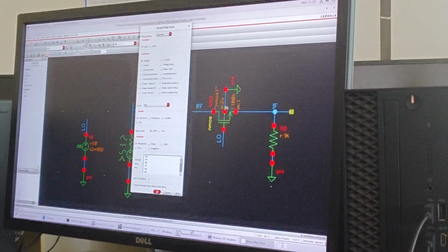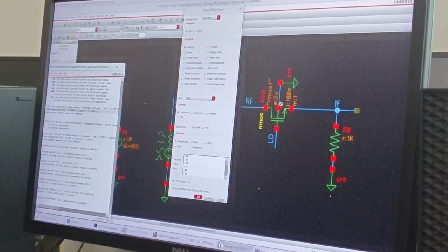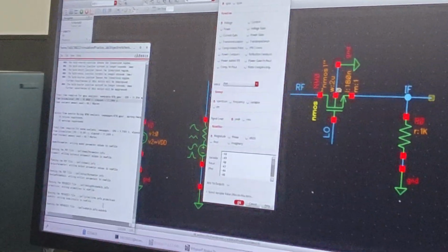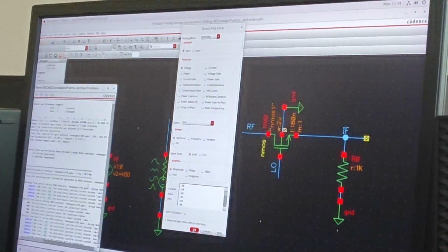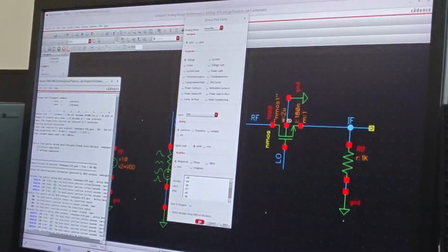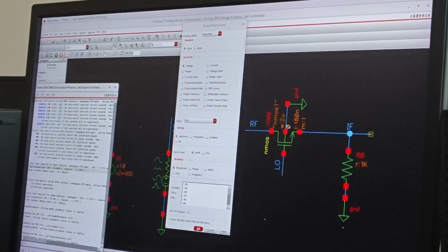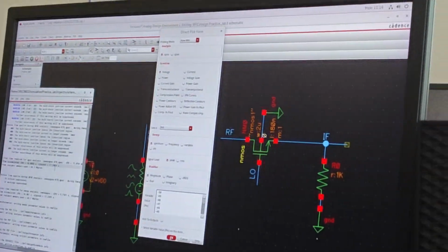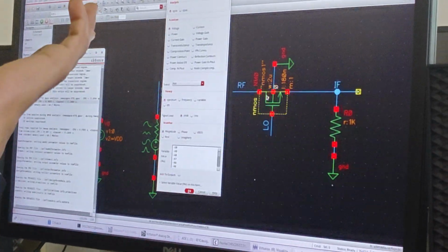Direct plot, main form. Don't forget to watch this log. Here sometimes these many notices and this many warnings will come. So check what those notices and warnings are, and understand whether it is really a problem or it is because of the input. Sometimes a few can be ignored, a few can't be ignored. So please check. Since we are giving plus 20 dBm here, of course it will not handle that, so those notices and warnings are coming.